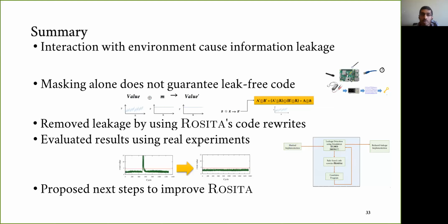So it's best if you can take this noise generation inside of the die. That's a hard problem to solve. It's not that practical to have a noise generator inside of the die, and it can interact with other things that are going on in the die too. That's a very hardware-specific way of doing this, but we can still do some work in the software area too.